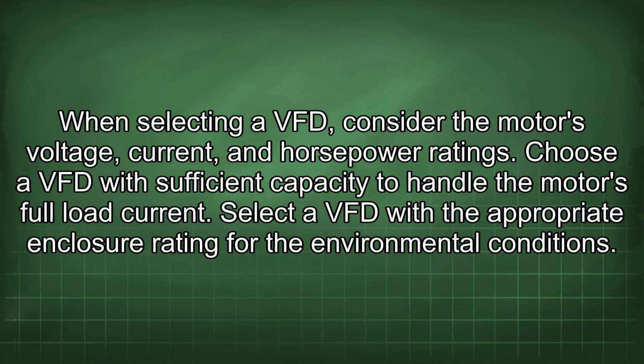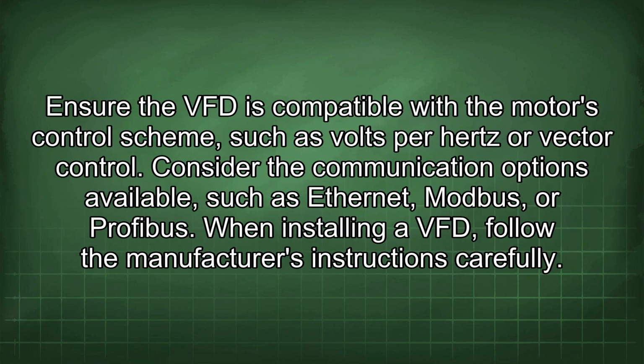Select a VFD with the appropriate enclosure rating for the environmental conditions. Ensure the VFD is compatible with the motor's control scheme, such as volts per Hertz or vector control. Consider the communication options available, such as Ethernet, Modbus, or Profibus.